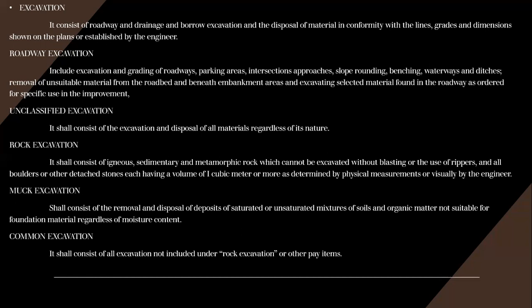Roadway excavation shall include all excavation indicated on the drawings within the limits of the cross sections, excavation of all materials for side roads and intersections, and the removal of existing pavement, sidewalks, curbs, and gutters within the limits of construction.